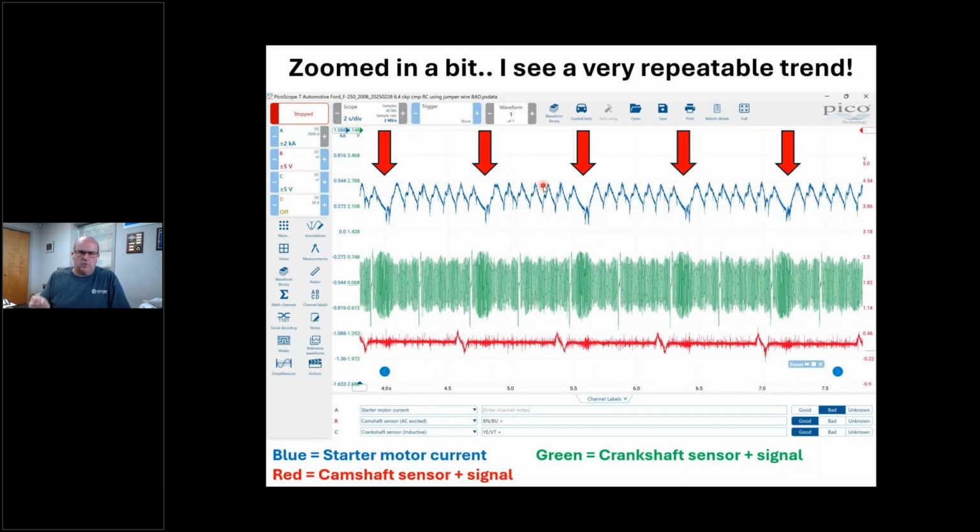If you crank this thing over and it's got a cranking cadence anomaly, we're not putting injectors in it more than likely, okay? Unless the injector pushed out of the head, okay? It's not the injector, which we know the 6.7 Powerstrokes, the early ones, did that. They broke the clamps and broke the bolts out of the valve cover. I'm sure you guys have seen that, okay?